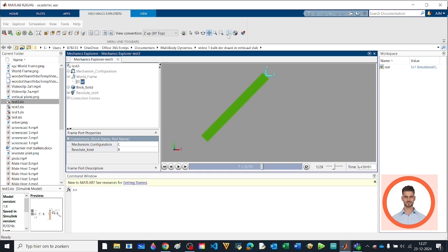When you start the motion, you'll notice that the world frame doesn't rotate. It's locked in place. If you check the Connections panel at the bottom, you'll see that the world frame is connected to the base frame of the hinge. Now, open the Revolute joint menu. It shows that the base frame is fixed, and just as expected, the follower frame rotates along with the hinge. To make things even clearer, use toggle visibility of frames to view either a single frame or all the frames at once.